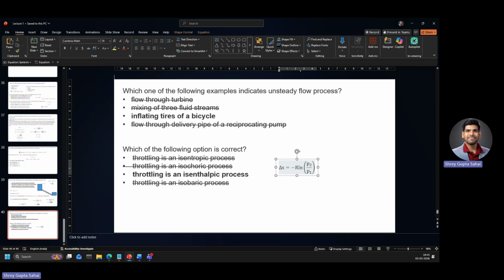And actually entropy is known to be reversibly affected only by heat transfer. So if you know that this is an adiabatic process and your entropy has increased, then for sure you know that this delta S is actually S generation.